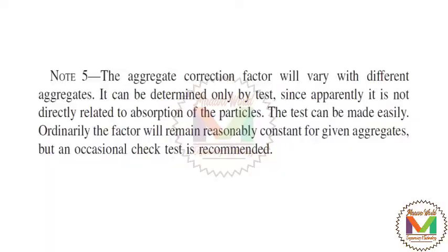Also, as per note 5, the aggregate correction factor will vary with different aggregates. It can be determined only by test. Since apparently it is not directly related to absorption of the particles, this can be made easily. Ordinarily, the factor will remain reasonably constant for given aggregates, but an occasional check test is recommended.